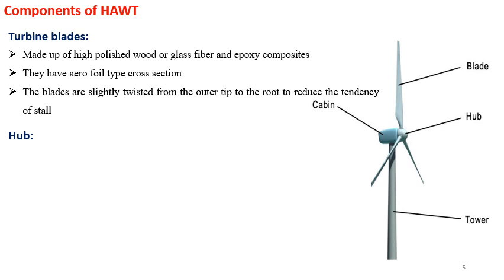You can even see a one bladed rotor with a balancing counterweight, which has some advantages including lower weight and cost, and simpler controls over multi-bladed windmills. However, starting requires high wind speeds, and vibration and other forces can be large in the case of a single blade.